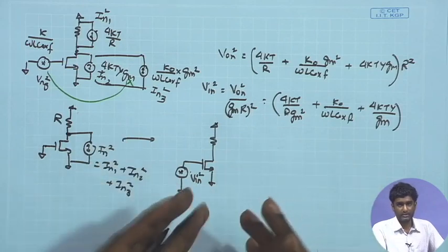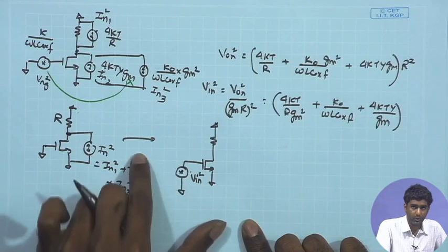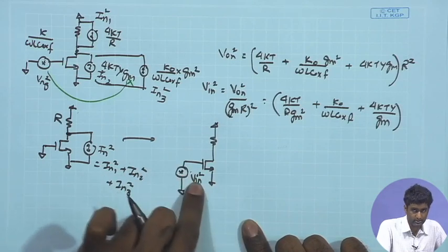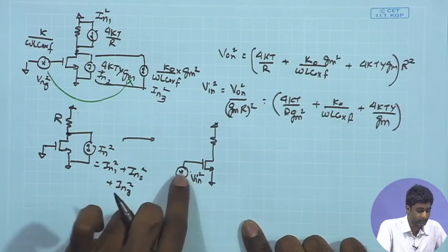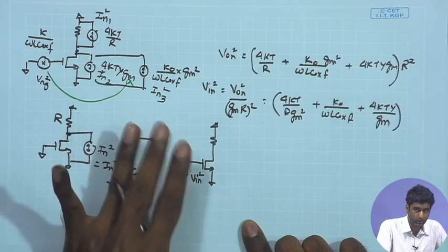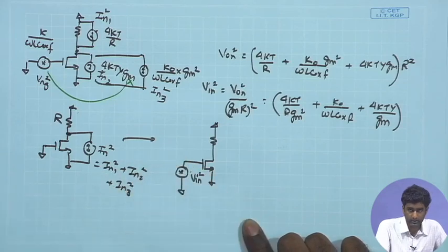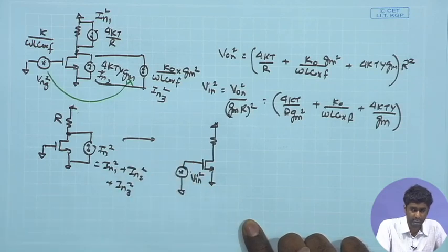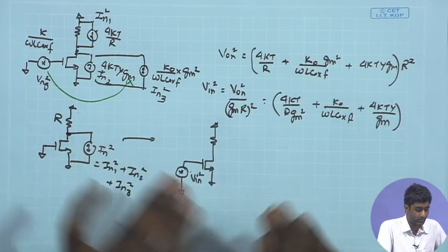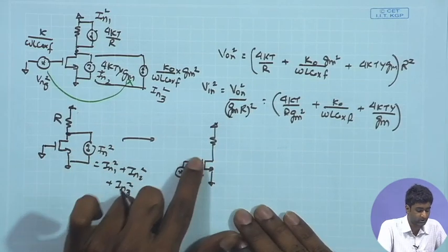For example, if I want 7-bit precision or 7-bit accuracy in the recorded data, and the data coming over here is 1 millivolt peak to peak, I would like to make sure that the VIN, the RMS value of this noise that you have at the input point, is lower than 1% of that 1 millivolt. So, this should be within 10 microvolt peak to peak. So, the RMS value should be within 10 microvolt approximately to ensure 7-bit precision for the overall amplification. So, it is a good way to compare the input signal with the overall noise contribution of the amplifier.